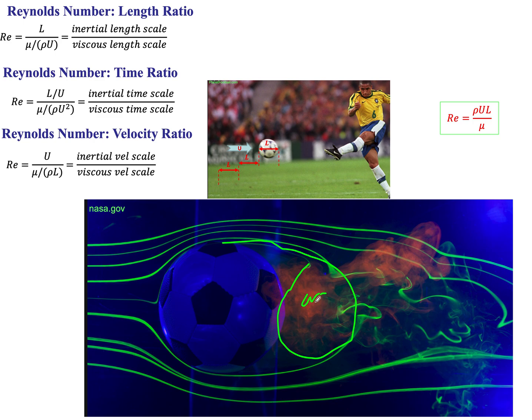And depending on the Reynolds number, which is defined as here, the size of this wake can be different, and the nature of this wake can be different for different values of Reynolds number, primarily because the relative sizes of the viscous length scale to the inertial length scale become different, just because that's the definition of the Reynolds number.